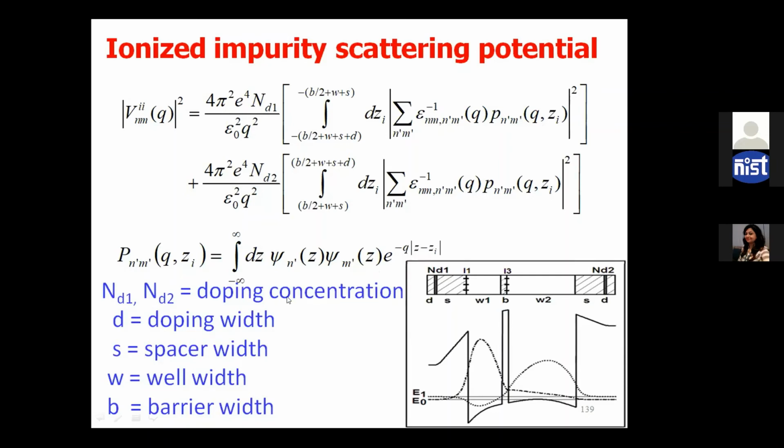What does it mean? To model the mobility, the scattering effect is important, and in scattering the tau is important. Tau means the transport time, the mean average scattering time, and that tau is modeled by using the V_T. In V_T we use the scattering potential, and if you take screening into account, we can change the scattering potential by modulating the wave function.